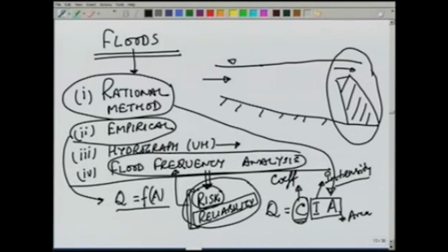So, to summarize today's lecture, we have looked at alternative ways of presenting the stream flow information. The hydrograph information we have discussed in detail earlier. We looked at the flow duration curve, which represents the dependability of flow: how much percentage of the time a particular flow will be available, or equaled or exceeded. The flow duration curves give us an idea about what discharge will be available for what percentage of time. So, we can find out an 85% dependable flow or 50% dependable flow and so on.